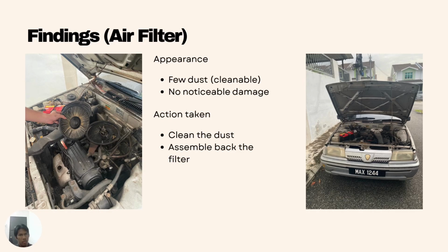Next is the finding. There is dust at the air filter, but not really any damage. So only clean the dust and then assemble back the air filter.